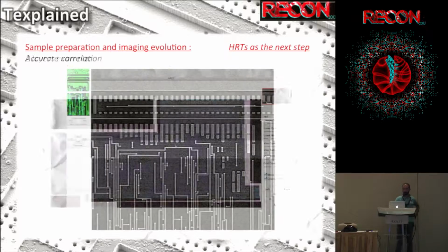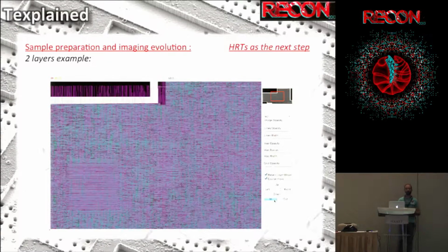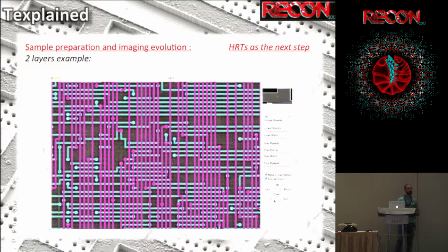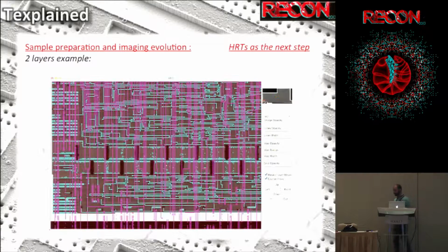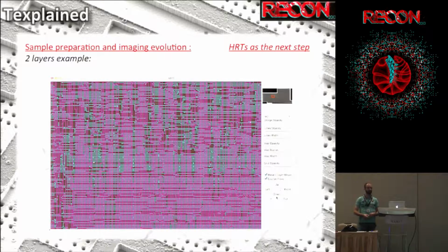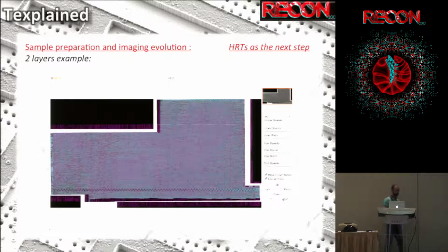And just after that, you have to align 2 layers together. And this is very easy, because now you align 2 layers that are lying on the grid. You have a bonus now, because you have used this principle. You can use a magnification which is very low for the top layer, because the lines are big at this stage. And then you can use a very high resolution for the bottom layer.